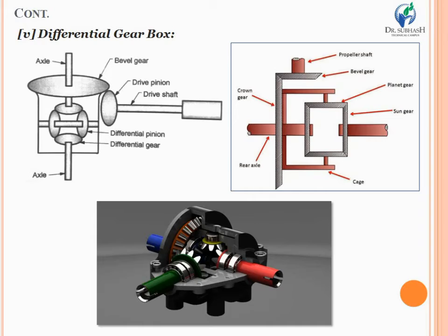Here is a simplified schematic of an automobile differential. The drive shaft connected to the engine drives the pinion that is connected to the bevel gear. Now the bevel gear is connected to the differential cage which drives the wheel axles, and the cage is connected to only one of the wheel axles, which connects the other axle only by means of the differential pinion. The differential pinion does not rotate as long as the speeds of the two wheels on the axle are the same. If one of the wheels slows due to turning, the differential pinion starts rotating to produce a higher speed on the other wheel.